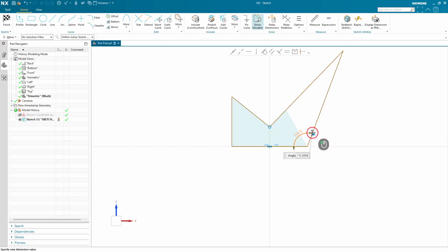Or you can actually click and drag a lot of stuff in NX. It's really nice to have that creative liberty to say, let me see what 70 looks like. Let's try like 101. So you can click and drag this a little bit and play with it, get it close, and then let's say at the end of the day, you're like, nah, let's just do 90. I don't want to click and drag to find it. You can go back to that box, type, hit enter, and now when I click away, that stays persistent. If you can see it, it is a persistent dimension. It's not going to go away when you click on the screen. So those two lines are also locked to be 90 degrees apart from each other, which is just like the perpendicular constraint on the other side.